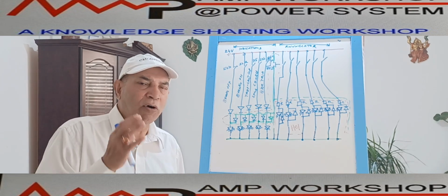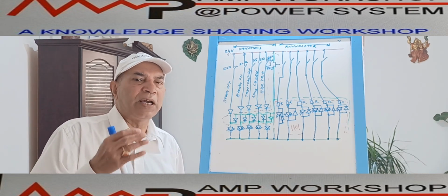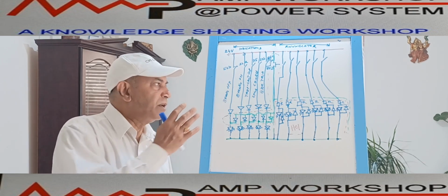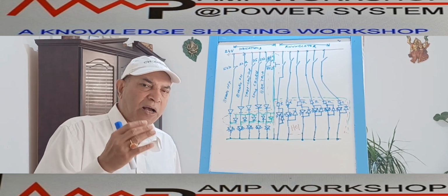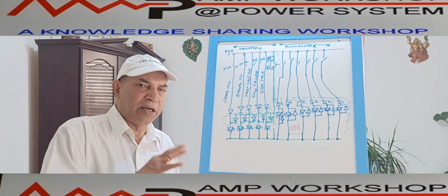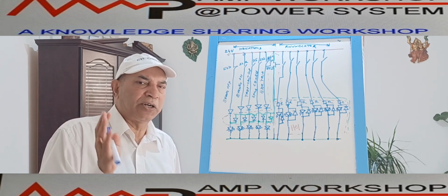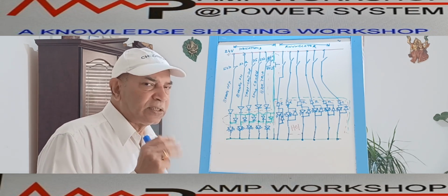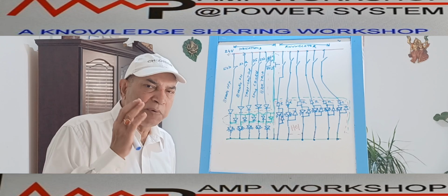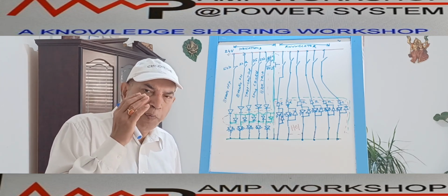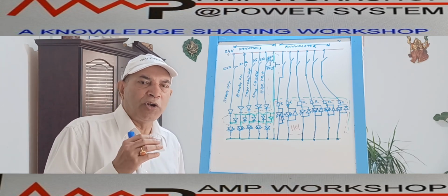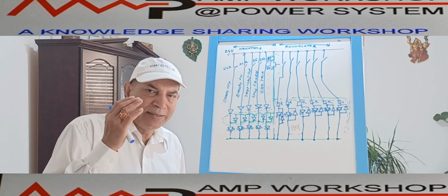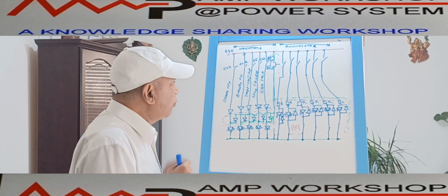Now we are considering that all the healthy operation will be monitored by the green color lamp. That is our present scheme. But if a customer wants a different color of lamp, that can be done, because LEDs are available in different colors. Okay, so now let's see how we do this. The circuit breaker open or off status we monitor by the circuit breaker NC contact. So we have put an NC contact.